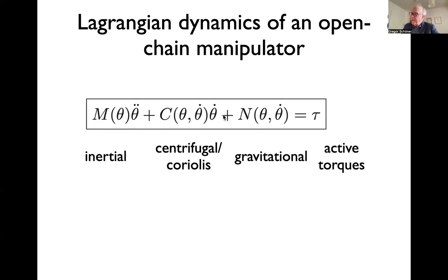These are these apparent forces. The fact that you're rotating means that it's not an inertial frame, right? Even if you have a constant rotation around a joint, then everything that's downstream from that joint is in a rotating frame, and there's a rotating frame's acceleration toward the center of rotation, right? So you're opposing the centrifugal forces.